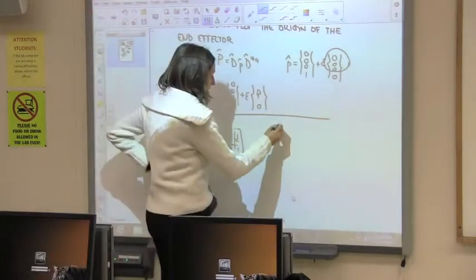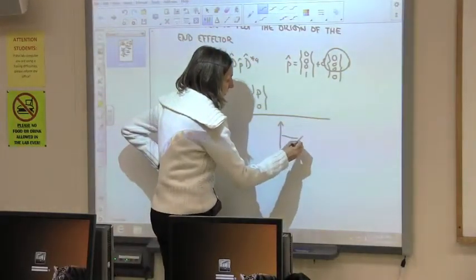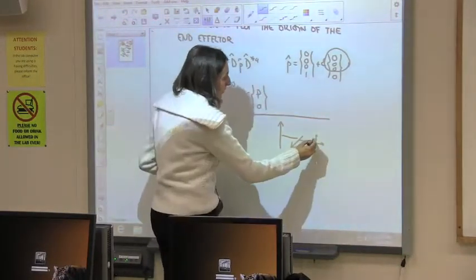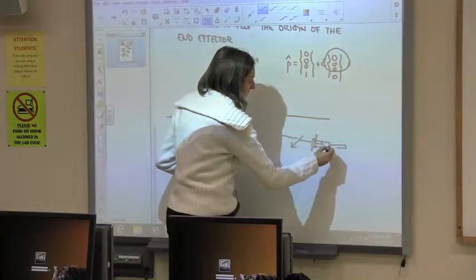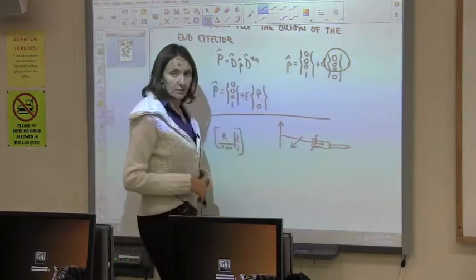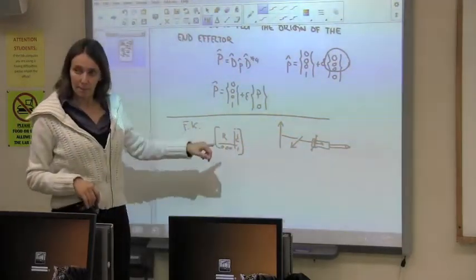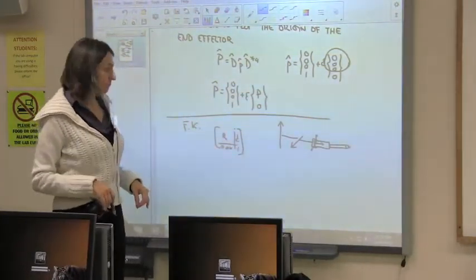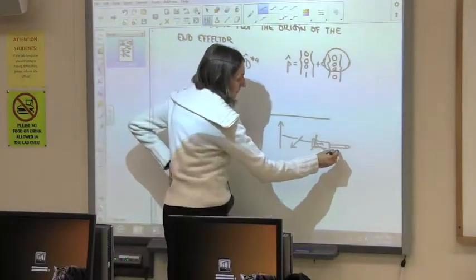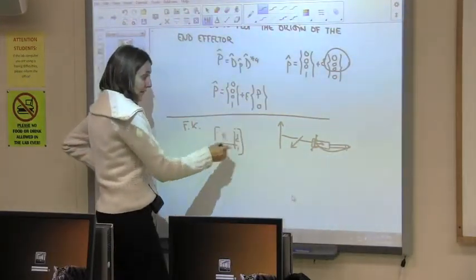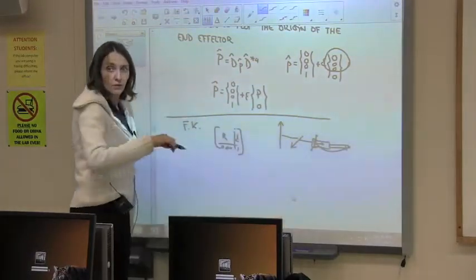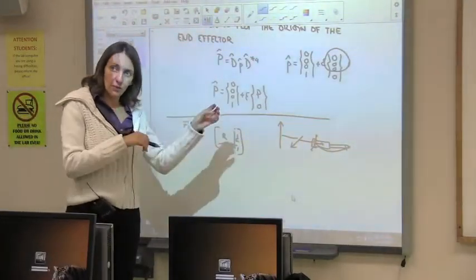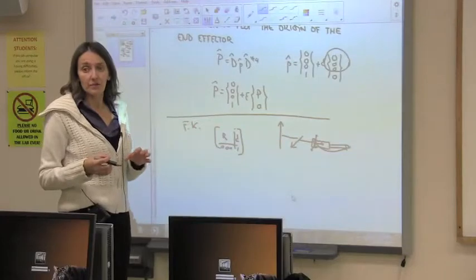For instance, let's take the same robot that we were solving, right? Imagine that instead of the center of the end effector, you want to put a tool here, a screwdriver, and you want to see what this point is. We can apply the workspace of the displacement to find the position of any point. So now you say, okay, I want this point. Then you apply this action to that point, and you will know where that point goes all over. So this mapping, if we just give this matrix, is really from the joint space to the space of displacements.